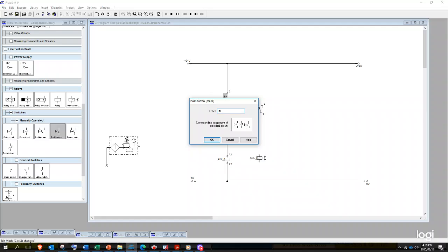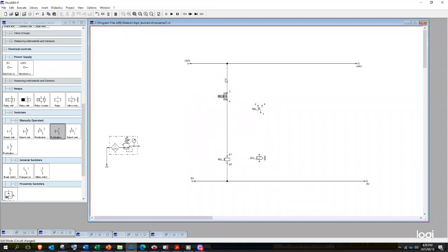Always label your work, even though you are not programming, on your circuit that runs through compressed air. You just have to label so that I know that this is your first push button, your second push button, and so on and so forth. So our basic circuit, indirect actuation, we have it. Let's try to make our work neat. Okay, so this is our indirect actuation.